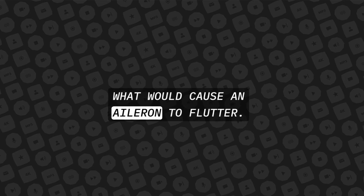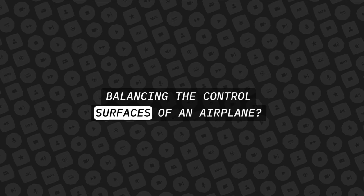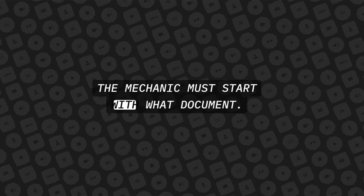What would cause an aileron to flutter? An out of balance condition on the aileron. Where can you find the specifications for balancing the control surfaces of an airplane? In the Aircraft Maintenance Manual. To establish conformity of an aircraft product, the mechanic must start with what document?